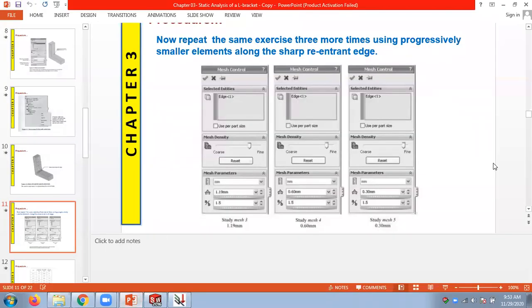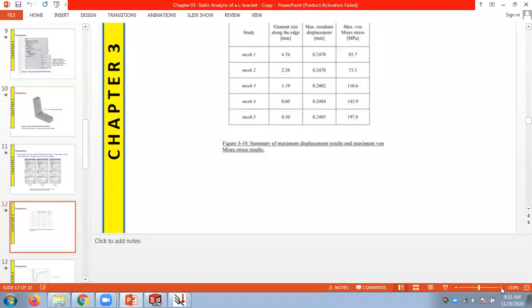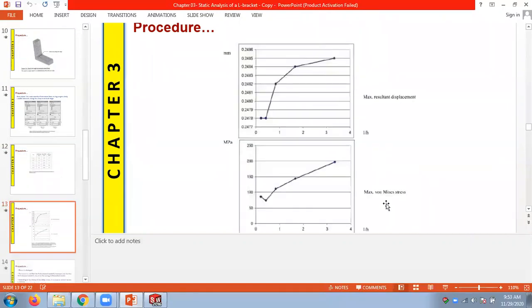So when you further refine the values, the stresses will go up. So it's mentioned in this table. So I started with something like 79, 80. So when I refine the mesh, actually in this one they have reduced the value. Then when you further refine the mesh, it has been increased. So actually it's climbing. The stresses decrease and increase. So here we cannot guarantee these results. So we have to have a converged value. So when you further refine the mesh, it will increase.